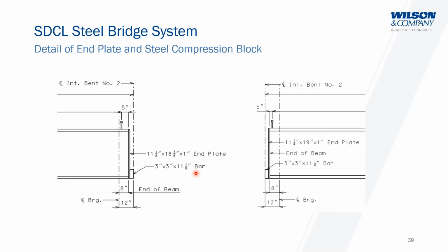And then there's our typical 3x3 bar. You can see how these bars are a little bit different in length. So not only are the heights different, but the widths are a little bit different between the rolls as well. I think we always used the same roll size between spans. So we never did venture down the route of, let's go with a 3-inch shorter beam height for the end spans.